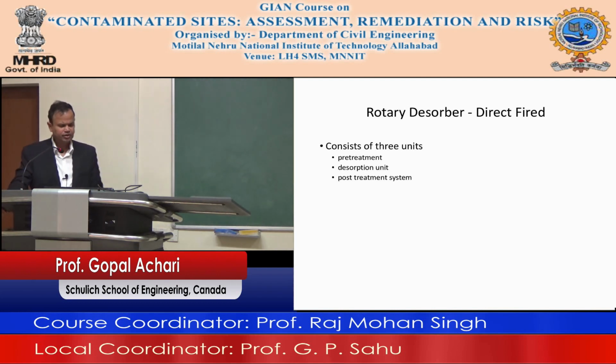In a direct fired system, you have pre-treatment, which is again what we talked about earlier, removing the bigger size material. Then a desorption unit where you desorb the gases, and a post-treatment, which is basically collecting the solids. The solids are then disposed of along with the clean soil. So that's the post-treatment.